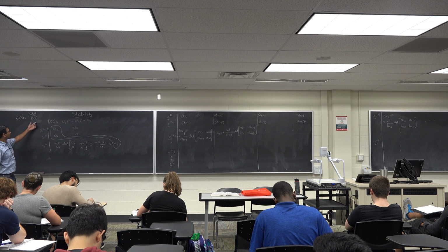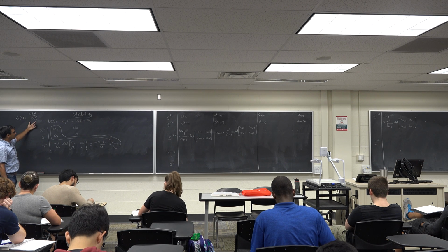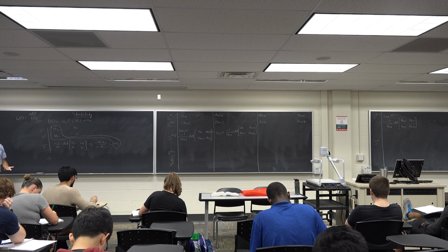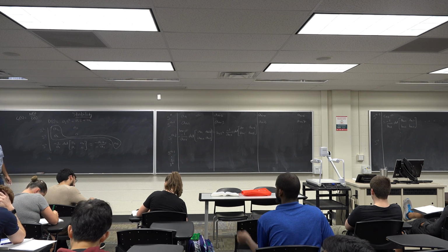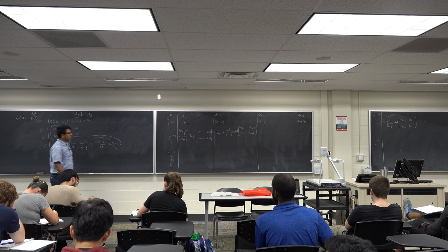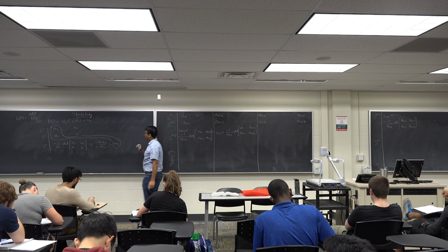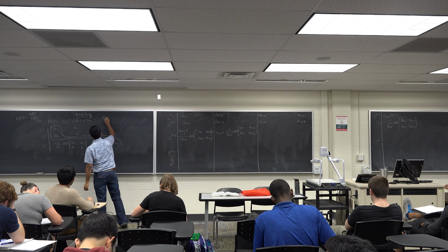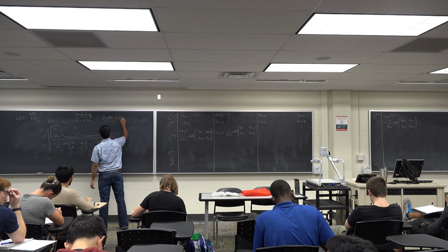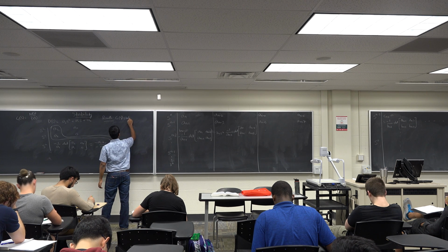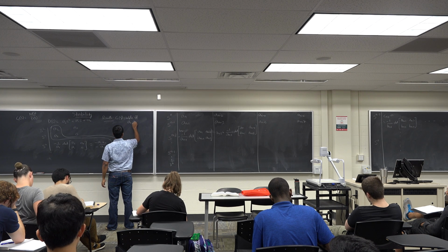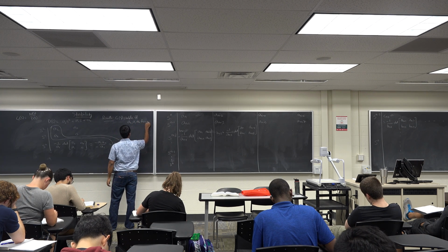So when is this system stable? The system is stable if A2, A1, and A0 all have the same sign, so either all positive or all negative. Then this system is stable. So the Routh array says G(s) is stable if and only if A2, A1, A0 have the same sign.